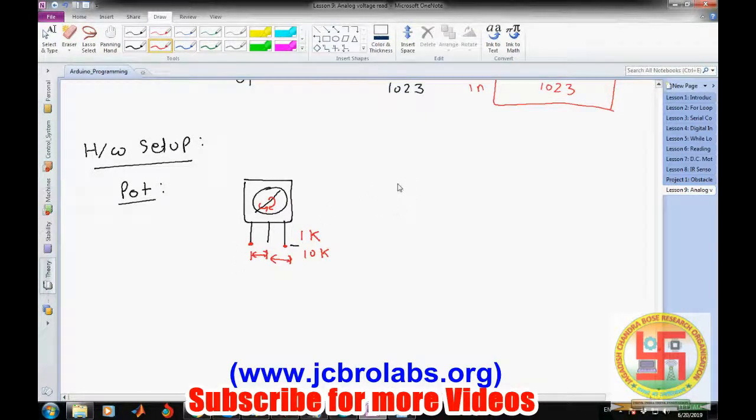So if we make a circuit like this, if we connect this particular point to plus 5 volt and this particular point to ground, then this V out will be 5 into R2 divided by R1 plus R2, where this one is the R1 resistance and these two pins are the R2. So just by changing this knob, we can vary this voltage.